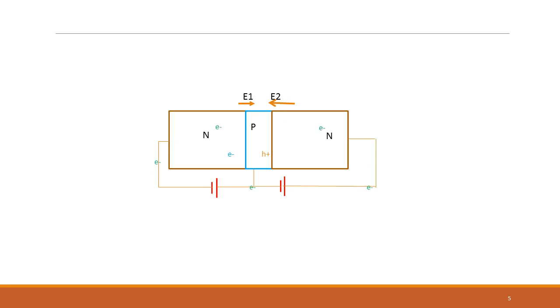In the same way, some of these electrons will recombine with the holes, which are the majority carrier in the p-type material. That also happens. And the minority carrier diffusion in the n-type, which is the hole, that current will also exist. It will get injected from the base into the emitter, and here it diffuses and this current keeps flowing. So it's almost exactly like the PNP, except that the minority carrier doping profiles have changed, so the minority carriers have changed in the base, emitter and collector.